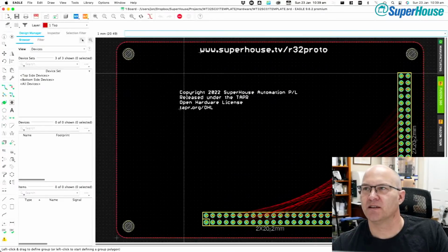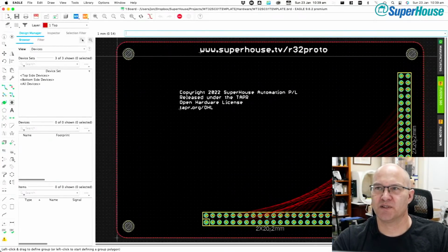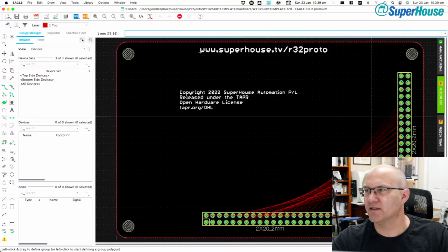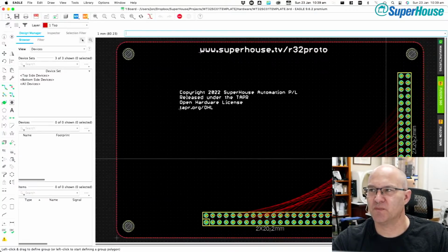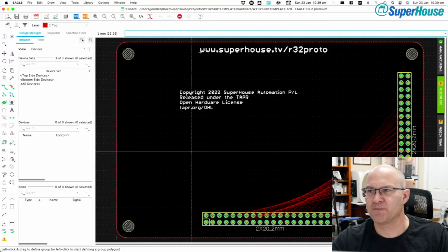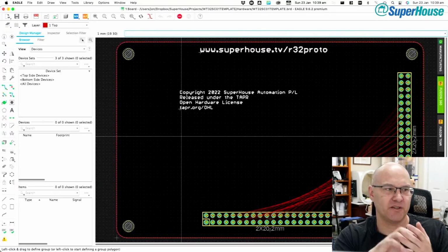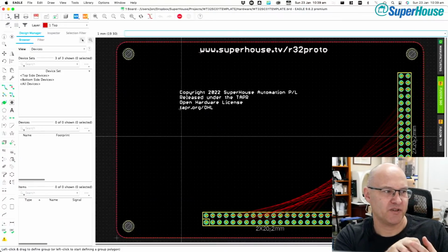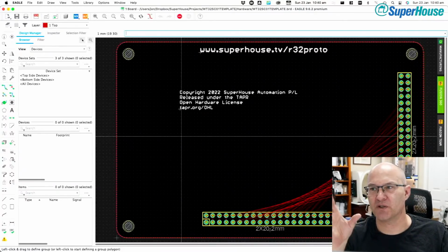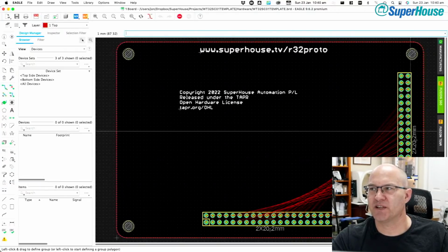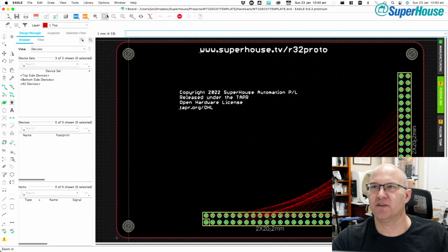Okay, it's done. And so what I did was I got all the dimensions, put the mounting holes in there, and put in both orientation connectors. So it's got the horizontal and the vertical orientation connectors, and they are in the correct place. So the idea is that when I want to start making a project that is based on this module, I can just duplicate these files, delete whichever connector I don't want to use, and away I go.